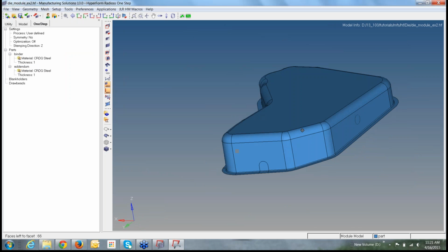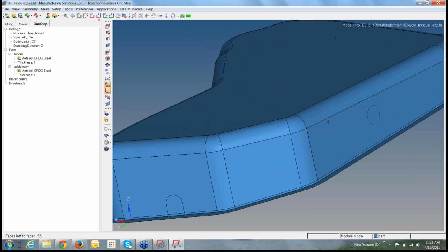Once you load your geometry, could be any format, could be IGS, could be step or parasolid. In step and parasolid format, the possibility of them being solid geometries is very high. Hence you need to extract the mid surface. Else if the component is already extracted, like the one in the graphics window, then you can directly start off with meshing. This is the mid surface directly. You don't need to extract the mid surface of this component.